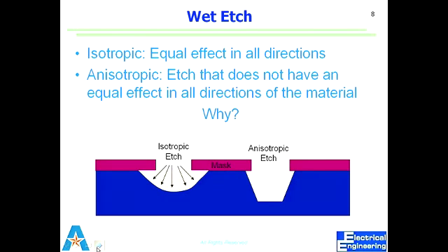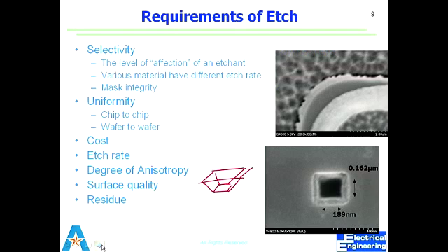And they may not get to the edge, right? If you do it long enough, ultimately it will end up in this pyramid where the equivalent planes of 111 will be exposed. There will be no 100 left in there. So that's something we do with silicon. What we use is KOH or TMAH. KOH is potassium hydroxide, TMAH is tetramethyl ammonium hydroxide. We'll look at these when we go to the etch part.